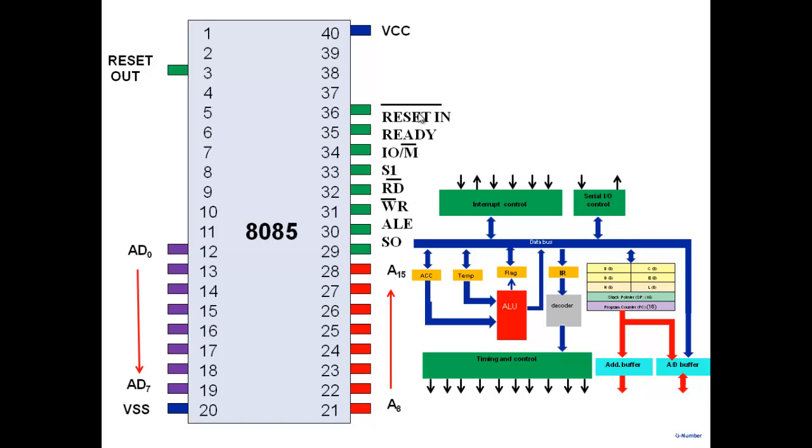There's, of course, a reset pin. You can reset the microprocessor. The microprocessor then goes back to the program counter will be stored with 0000, goes back to the first place in the memory here. Registers may be initialized, so all of that. And when you give a reset in, the microprocessor also produces a reset out, because there are other systems connected to 8085. So when you're resetting your microprocessor, you may want to reset other systems as well. Okay, so it allows a reset pin out also. So these are all the control signals that are available here.